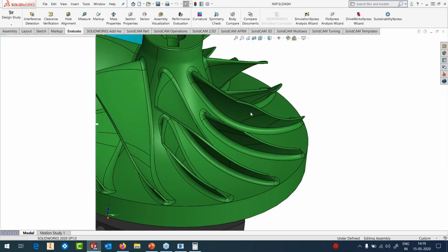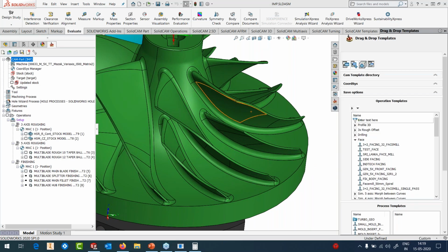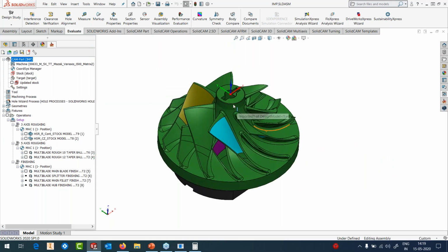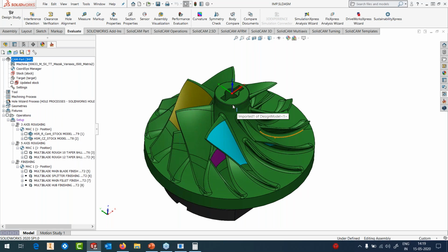Sir, the most important thing here is going in stages. You don't machine right from top to end in one go. You will machine in stages, especially after roughing. We generally recommend aging of the part, though some people don't do that, because roughing is a really stressful process and it does induce a lot of stresses. In some cases, some of my customers are doing it in stages. They machine the top, then machine the bottom, wait and allow it to age, put it back, and then do the finishing. Thereby, it reduces the stresses, and the reduction in stresses will reduce the buckling of the blades, basically.